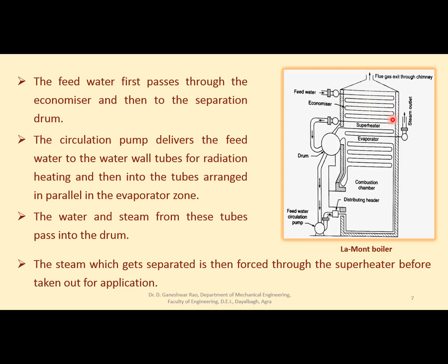What is the advantage of it? The advantage is that the feed water which is going into the boiler for getting converted to steam attains high temperature without expenditure of fuel, right? So here fuel consumption will be less to convert it into steam in the combustion chamber, right? So feed water passes through the economizer